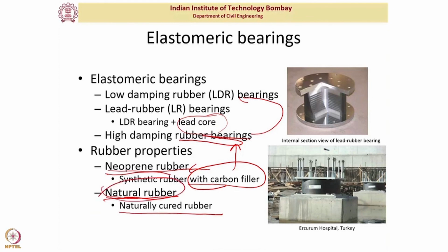And you see you have foundation pedestals here. Below this you might have a raft foundation or something else. On top of that you have this foundation pedestal, which is typically very rigid, and this isolator is connected through these external bearing plates and bolted to this pedestal here, and on the top you again have the same bearing plate, and then you can connect to the concrete columns or steel columns as the case may be. And you would have several such bearings in plan.